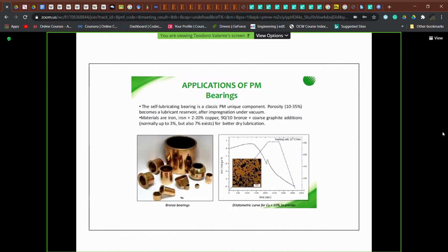But we do have also others, even though they are niche applications, but interesting, by using the possibility to control, as we said, the final porosity. Because if our aim is to eliminate the porosity completely, we can make our sintering step up to a stage for which the solid state diffusion is able to eliminate the porosity in the green compact.